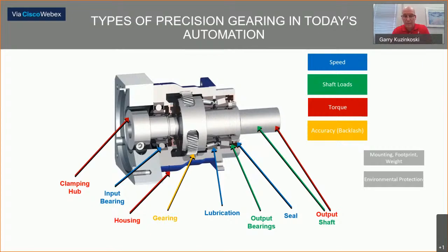The input bearings have to be selected for that operation. If I have a lower cost bearing that can actually meet those speeds, there's a purpose for it if it's more of a power transmission device, but I always want to make sure that the input bearings can withstand, say, a 4,000 or 5,000 RPM servo motor versus only an 1,800 RPM, maybe induction motor.